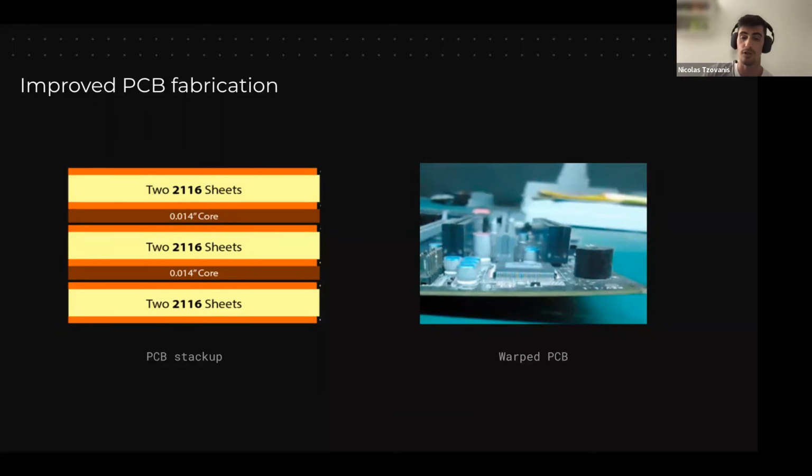And in that process of soldering, the whole PCB gets hot, so that actually solder melts. And then what happens is, if you have different materials that deform or get hot and expand at different rates and shapes, for example, if you have copper that is not properly or evenly distributed, you will see that the PCB will warp or will bend in some sort of way.